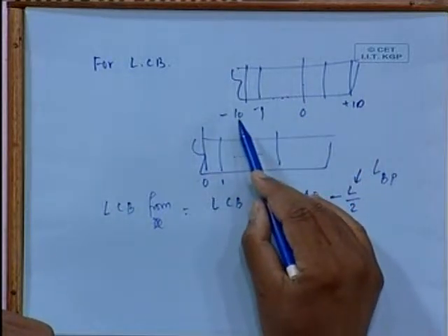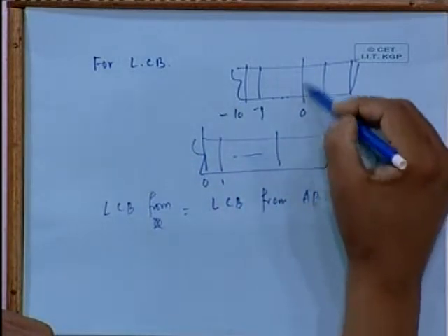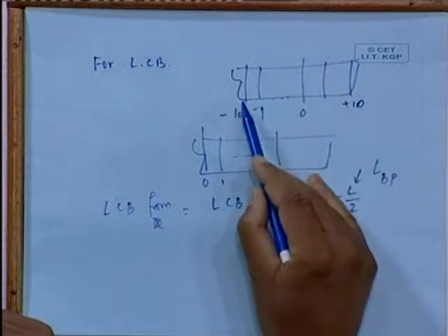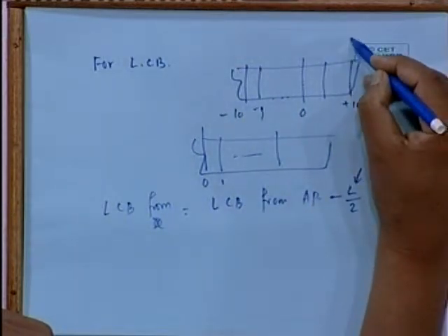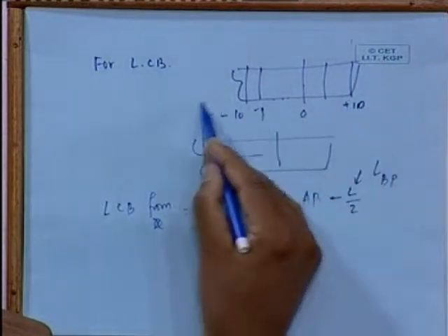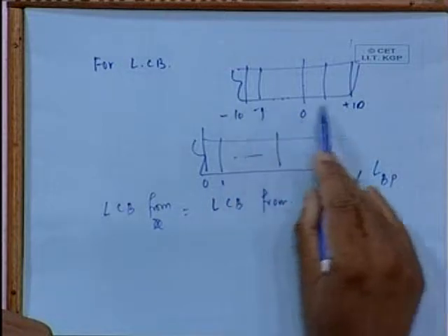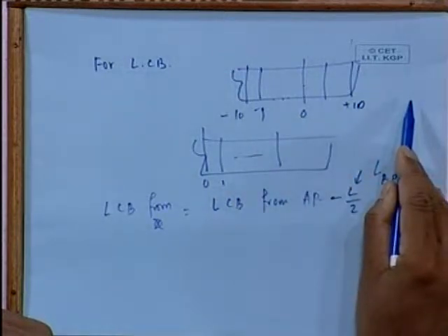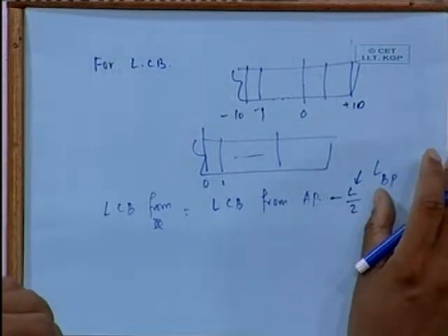Many of the earlier textbooks take negative stations, with midship as the zero station, but the convention followed differs. In America, for example, they sometimes take this to be 0 and this to be 20. They go in the opposite direction. In Britain we go from this way forward. So it is a question of convention. Nothing is lost on that.